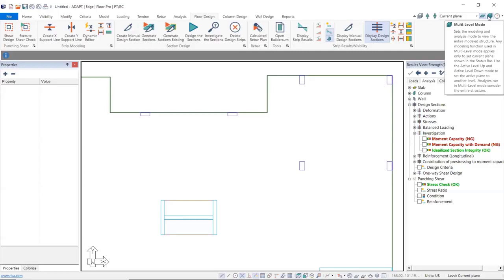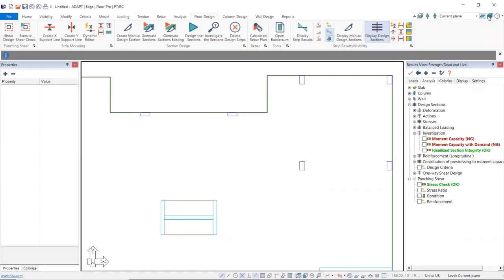And as we'll discuss in a moment, we can process a global model under different stiffness assumptions using what are called usage cases. Each unique set of reactions is stored and can be used for the design of different aspects of your building when you're using usage cases. This means there is absolutely no reason to export or import reactions between programs. Builder will keep all of them within the same model.